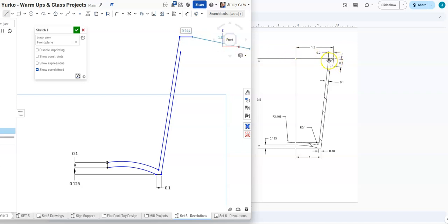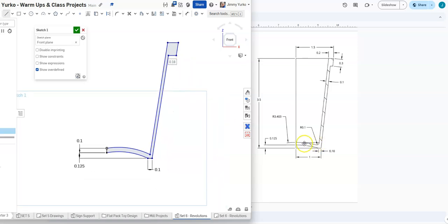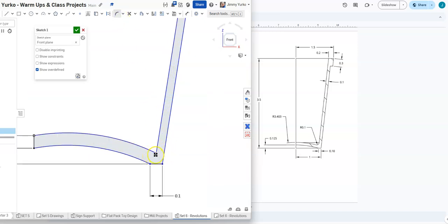We're going down parallel to the inside. So parallel to that. And it does appear to be a horizontal line there. So we'll go there and there. And that closes our shape in. We don't have our dimensions on it yet, and we're still missing our fillet. So let's go ahead and grab that fillet at 0.1. So take the sketch fillet tool, zoom in, select the inside radius.